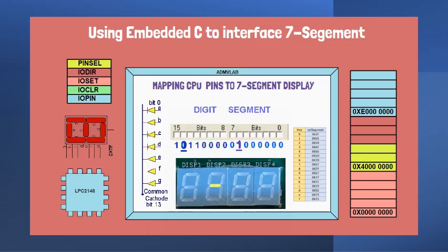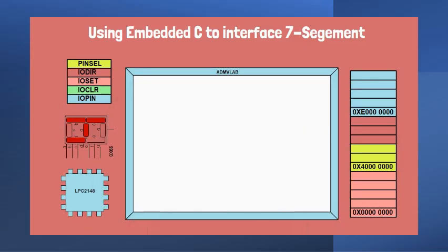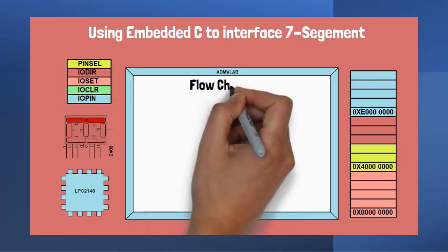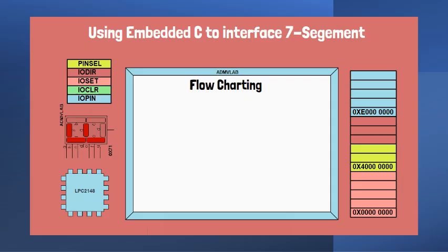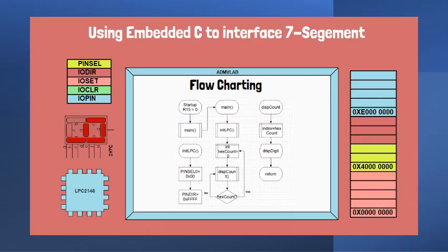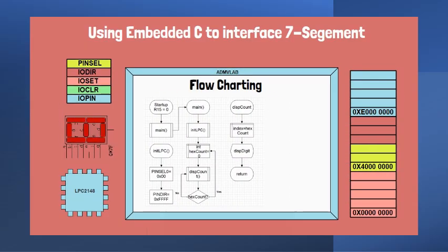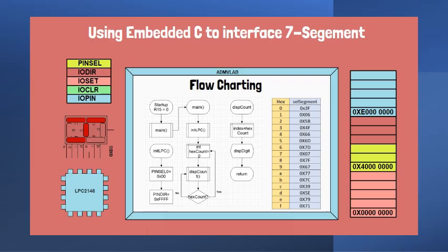Once we write the truth table or load this data into an array, we can use the array data to display hexadecimal numbers on the fly. Before we actually code, we will use a simple flow chart to visualize the steps required to implement our second lab. On reset, the processor program counter R15 is set to 0.